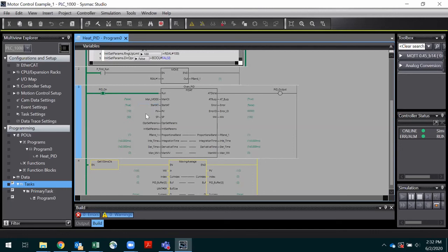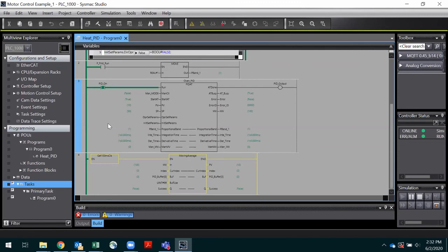The auto tune won't override if you have 0 on any of those parameters. They have to be non-zero to be auto tuned. I've never tried the other way. I just know that setting them to 0 disables either integral or derivative modes. That's something I could find out pretty easily. So I triggered the start AT. Looks like your floating average block isn't doing much right now.